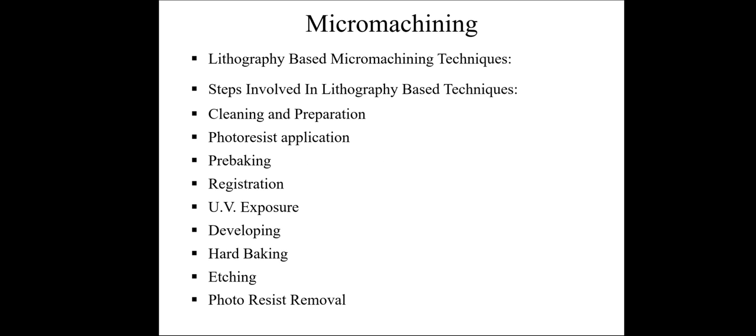Next one is the development. The behavior of resist film on exposure and development depends upon the exposure energy and whether the resist is positive or negative. As the exposure is increased above threshold energy, more of the resist film remains after the development, such that at 2 to 3 times threshold energy level little of the resist film is dissolved. For positive resist, the resist solubility to its developer is finite even at zero exposure energy. The solubility gradually increases until at the threshold the resist is completely soluble.